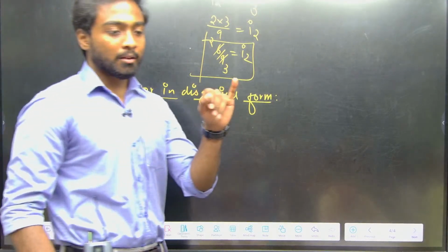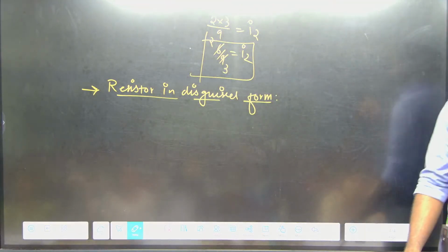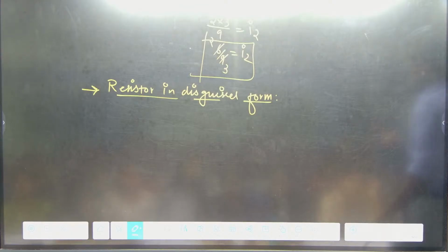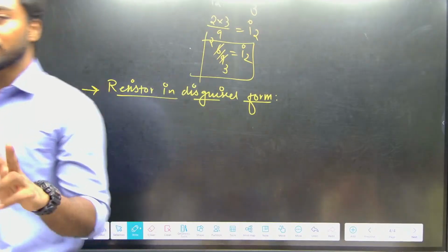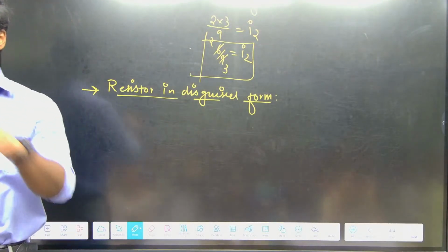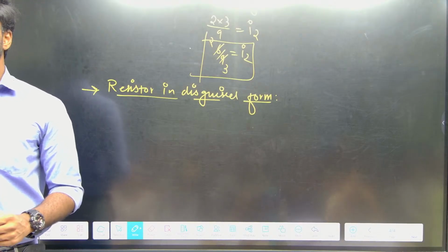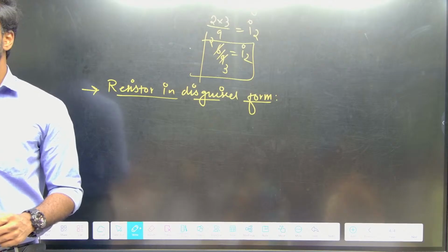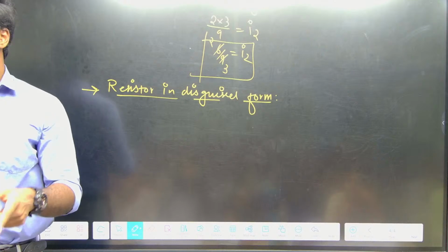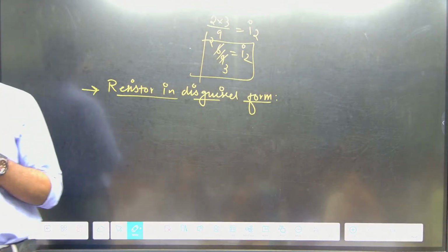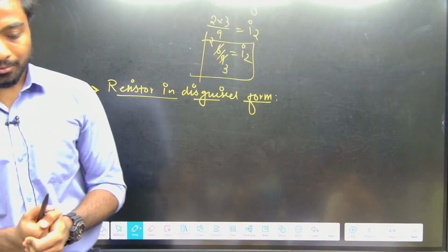So we have completed the Wheatstone bridge problem also, like in capacitance we have completed the same concept, only we are going to see it in resistance also. R1 by R2 is equal to R3 by R4. When the ratios are same, in between whatever the resistances are there, I can neglect that resistance. Any doubt? The same concept, C1 by C2 is equal to C3 by C4. When the ratios are same, what can I do? Whatever the device, either it can be a capacitor or a resistance, I can neglect that. Now write down the first one.